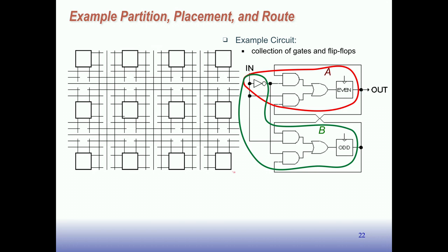Okay. If that's the most efficient thing to do, in this case it is. All right, so then this partition has 1 input from here, 1 input from here, 1 input from here. It's the same as the other, uses 3 inputs. The other LUT input would just get tied to some constant 0 or something like that. Effectively doesn't get used. All right, so that gives us kind of the optimal partitioning of this thing.